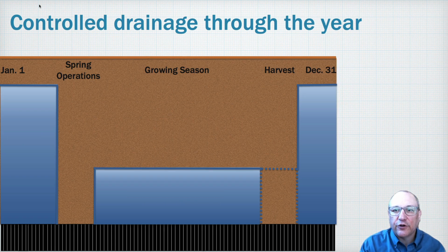As we discussed in the introduction video, though, controlled drainage only controls the outlet elevation. So although we have these control structure settings, the actual water table height will still depend on precipitation and evapotranspiration. For example, on poorly drained soils, in most years, we begin the season with a shallow water table necessitating drainage. After the outlet is raised again, it takes timely rainfall to be able to raise the water table again.